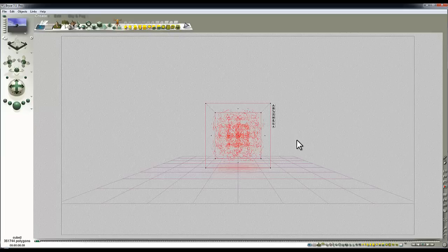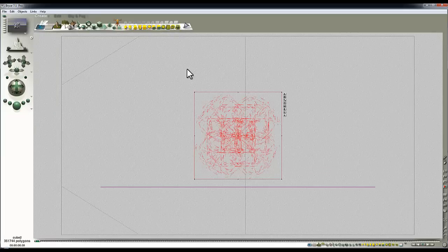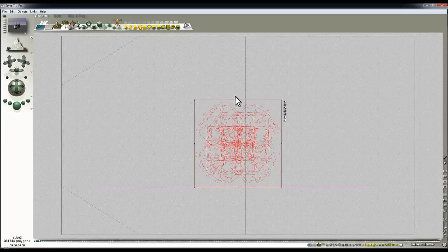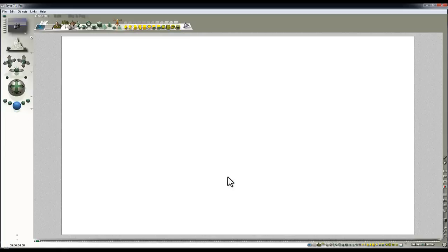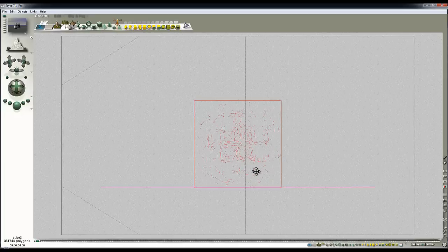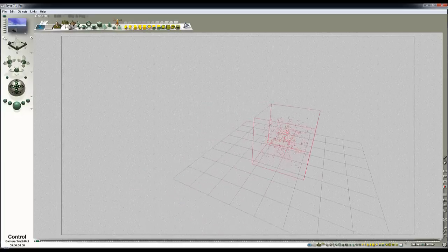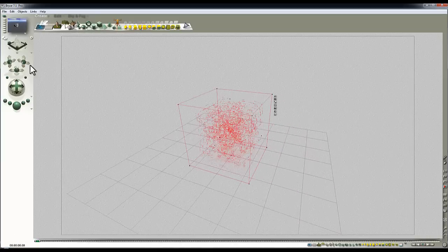Right, and at this point, press 3 for the right hand view. You see it's not at ground level, so we can land it, but usually there's a bounding box that's bigger than your mesh anyway, so it won't be properly landed. Render from this view, and you might be touching the ground, or there might be a slight gap. To me it looks like there's a slight gap there, so just drag it into the ground to make sure it's touching the ground so it's not a floating object, and then you can start setting your scene up in Bryce.